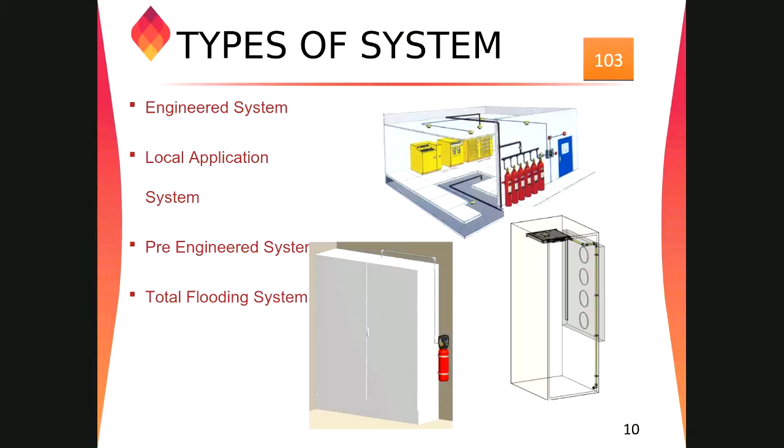The meaning of the total flooding system is that it is a system that consists of a supply and distribution network, right? So we have many cylinders connected to a common header, and those headers are going directly to the room. So the flooded system is the complete room. In case of fire, all the system will be discharged, and it will flood the room with that gas and extinguish the fire. This should be done in hydraulic calculation software to install at the site.